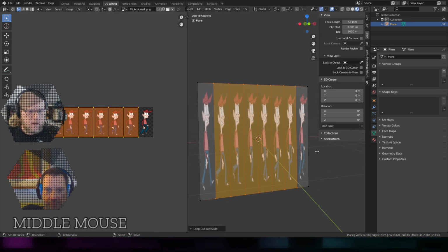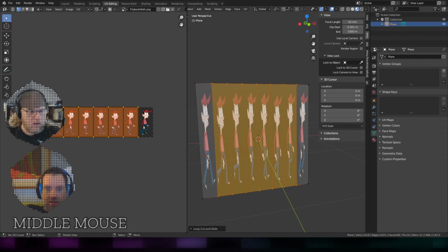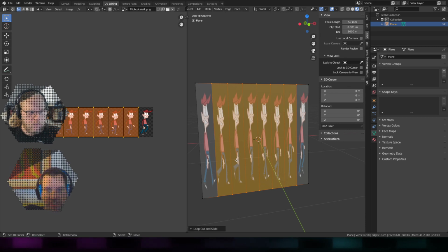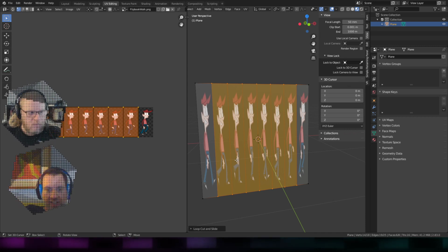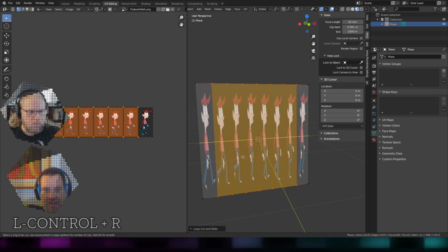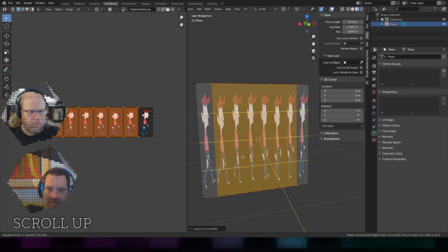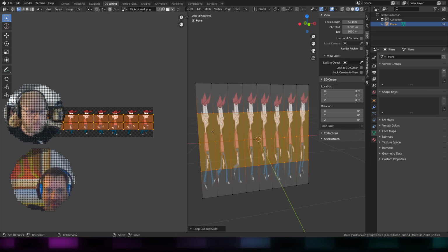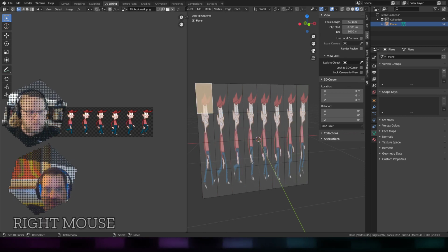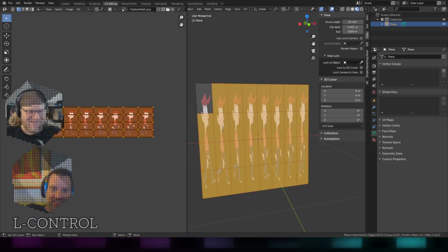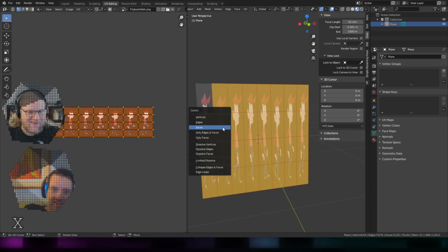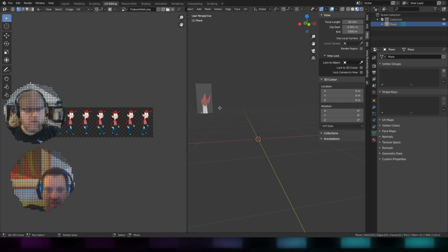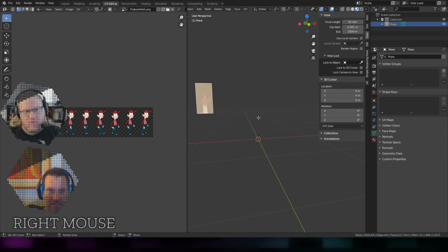But your height is not the same aspect ratio. Height's not right. So an easy way to get the height right, since I know it's a 1024 by 256: 256 goes into 1024 4 times, right? So I'm going to do Control R again and split this one up 4 times. Like that. And now I know one of these corners is the right size. So this is kind of lame, but I just selected the corner and then I hit Control I to select the opposite, and I deleted them. And then you could probably also scale it. You could scale it as well. I'm just tinkering, and whatever works. This is how I do it.